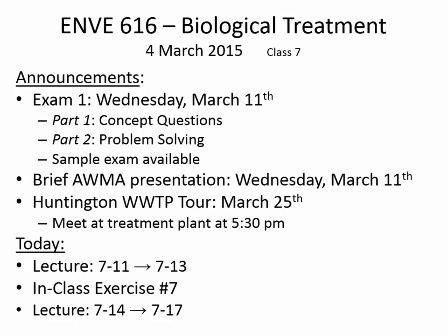The other thing you need to mention is that if we don't recirculate, then the biomass concentration in the aeration basin isn't high enough. So really, the purpose of recirculation is to get the biomass concentration higher, because the natural biomass concentration is going to be very low. We need to get it up around 2,000 to 5,000 grams per cubic meter. So it's to increase the biomass concentration, and as a side note, recirculation also has the benefit of very hungry bacteria by the time they are recirculated. All right, so good. Any questions about what concept questions look like?